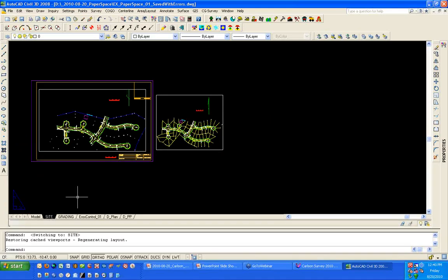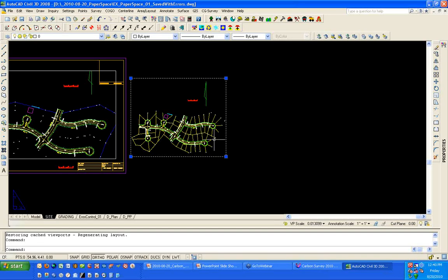So I just want to cover a few things here in AutoCAD that we've talked about, so you can see how to do it from IntelliCAD and see the differences. One of the major things that I really do miss working in IntelliCAD from AutoCAD is the ability to easily set the viewport scale. I do not have this one locked. As soon as I selected it, I could tell it wasn't locked because AutoCAD gives me this neat little thing on my status bar. So I've got a padlock, so I can actually lock or unlock that viewport right from here.